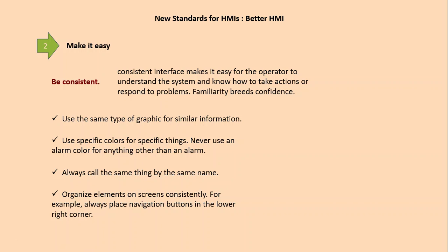Whatever design we use in HMI should be consistent throughout the whole HMI design, or even better, follow an industry standard from one plant to another, and that way operators get trained automatically. Even hiring one operator to replace another will be much easier, because he is familiar with another plant, and those are similar standards.